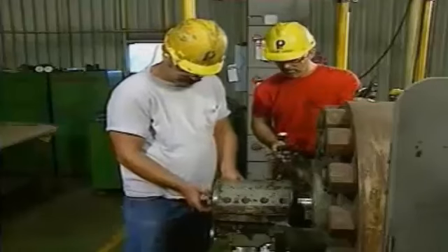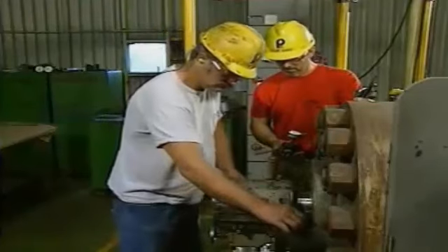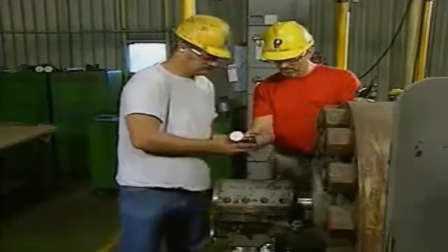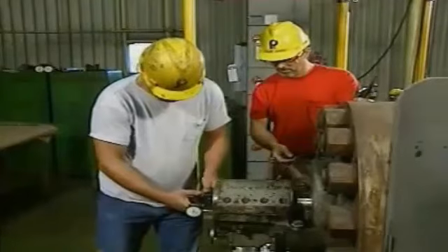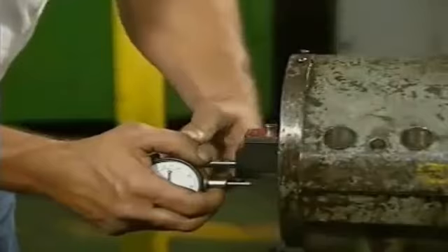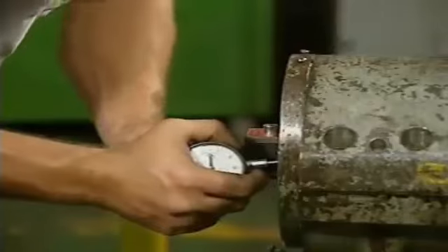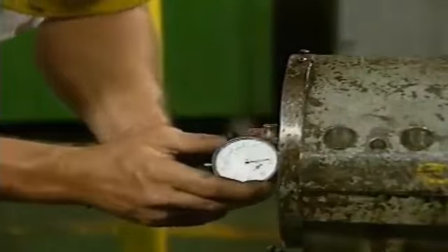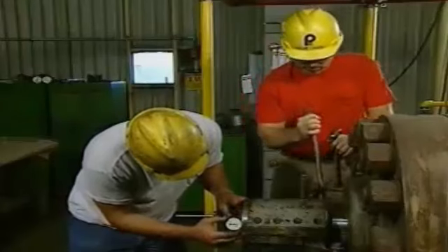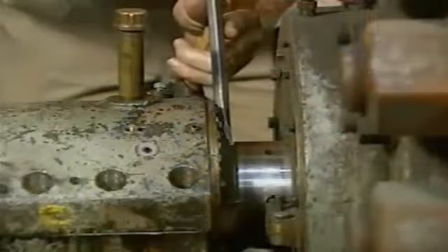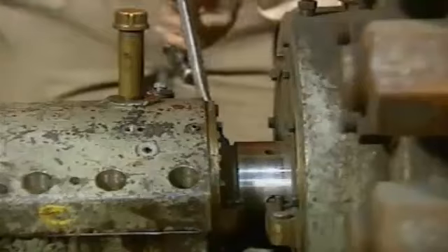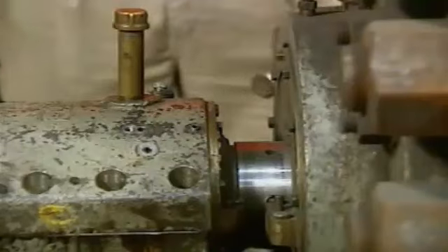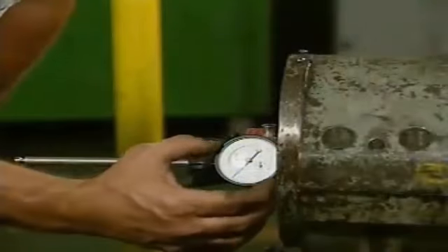One mechanic removes an access plug from the end plate of the housing and sets up the dial indicator to contact the end of the shaft. He secures the dial indicator to the end plate so that it will not slip as the reading is taken. When the dial indicator is in position, the other mechanic moves the shaft as far as it will go in one direction. The dial indicator is then set to 0.